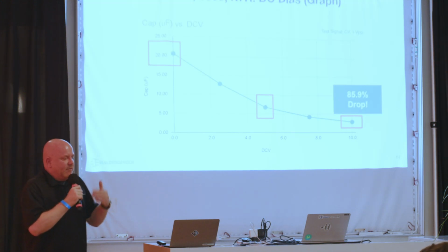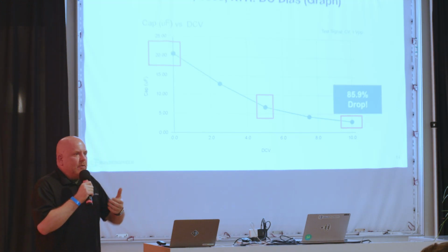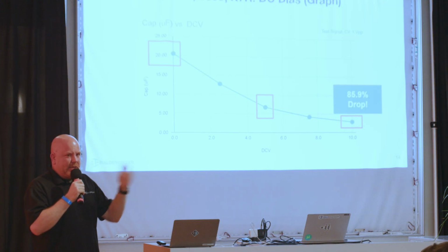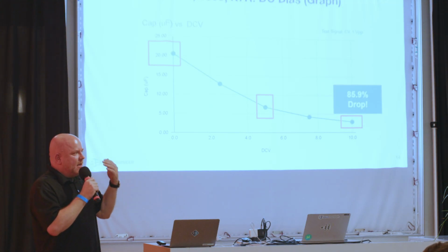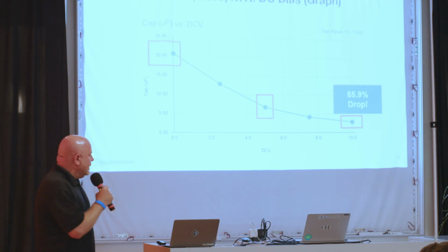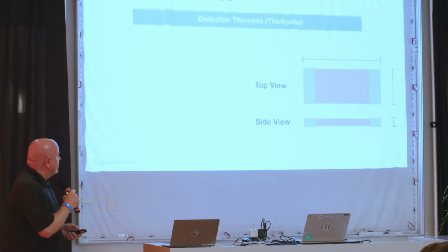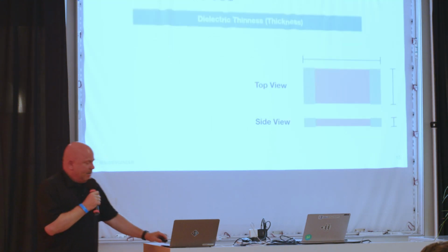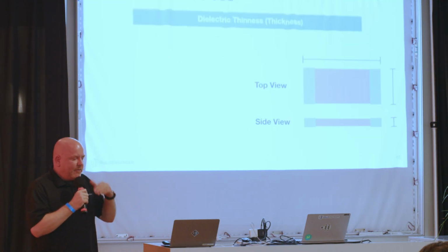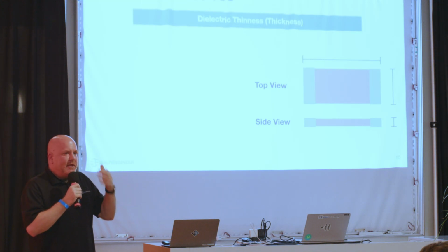You know, the old adage of, oh, derate capacitors by 50%, well, the reason you do it for ceramics is not to extend their lifetime. It's to get more effective capacitance out of them. Now, I wanted to give you a couple of guidelines because when you first start to realize how bad this is, the next question is, well, how do I pick the right capacitor?